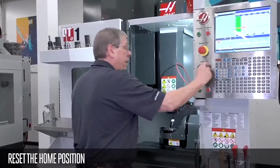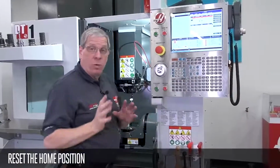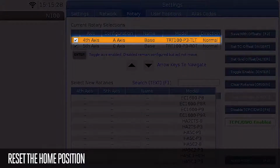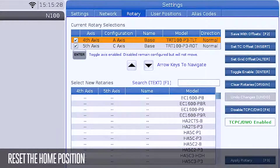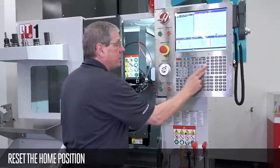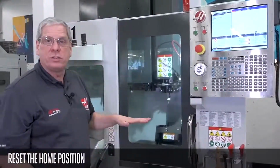I'm going to jog my indicator up and out of the way, and then I'm going to go back to my rotary setup page. I make sure that the fourth axis is highlighted, and I'm going to press Insert to set TC offset. I press Enter to accept the prompt on the screen, and it resets my tool changer offset. Now, when I zero return the axis, it's going to return back to that flat position.